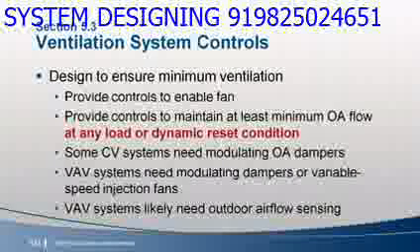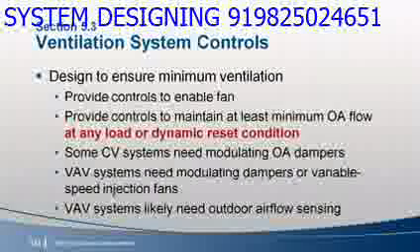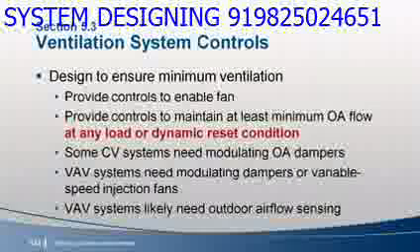Of course, although not yet required by Standard 62, most designers know that most VAV systems need to sense outdoor airflow as a means to modulate the dampers or fan motors.